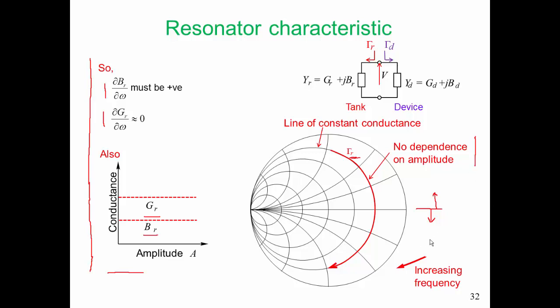We will not be operating our oscillator near the unit circle, especially when we're above a gigahertz or so. We will be inside. We will be in this region. And for the oscillator that we're designing in this case study, this is about where we happen to be. Now we have a way of lumping our resonator design criteria into the behavior of the reflection coefficient.